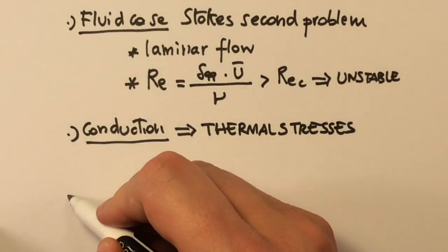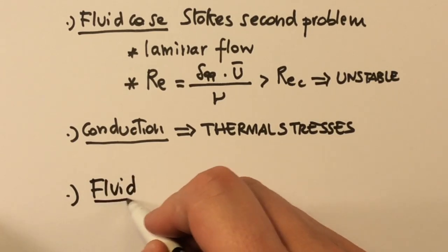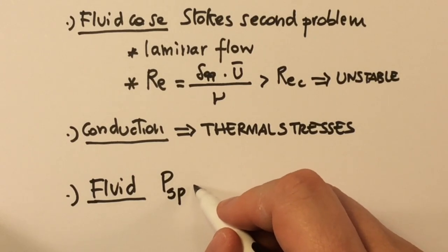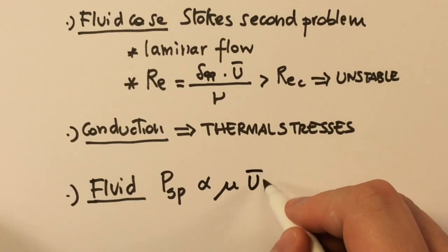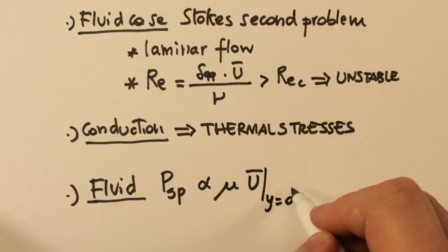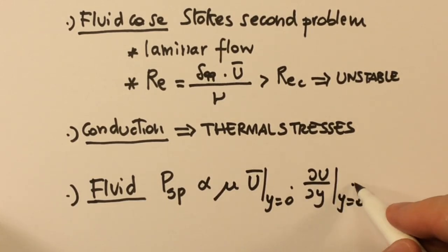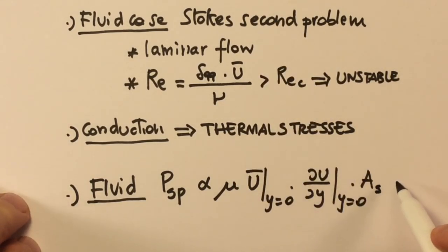And the next comment is that in the fluid case, we computed the power injected into the fluid, and we found it to be proportional to mu u bar at y equals 0, times partial u partial y at y equals 0, times the surface area. So in that case, we have a force times the shear stress, and we computed this in units of watts.